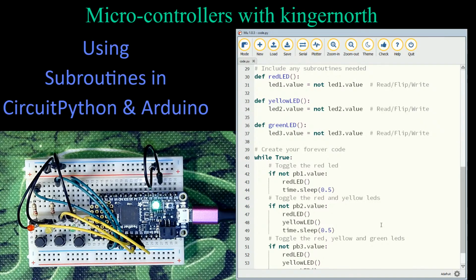So it's actually pretty neat what we can do with subroutines. We can actually save ourselves a lot of room. This is much more organized than if we had to write that code and keep repeating it everywhere that we wanted to use it. So anytime you're going to repeat code, by all means, create a subroutine for it. You'll actually find out what it's good for. And if you're doing it once, you write it in the code like we did when we started with the Arduino today. We wrote the code once, we tested it, and then we created a subroutine to replace it. And then we just kept going from there on and on.